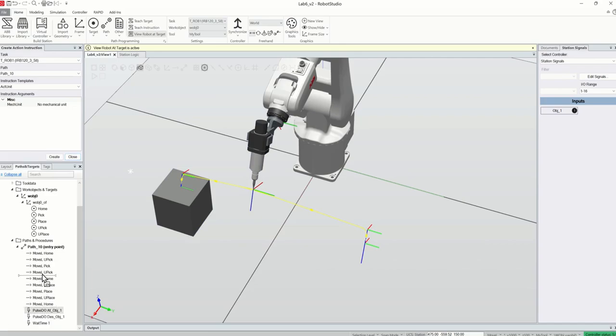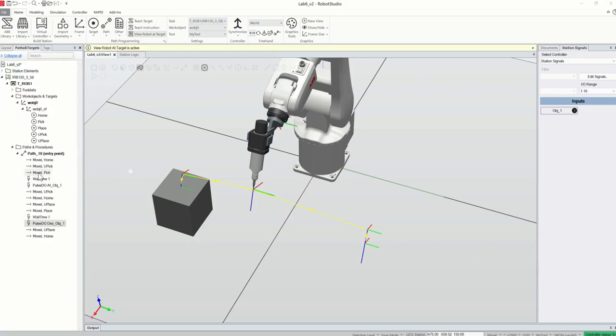So what I'm going to do is go to the pick position, then wait for 1 second, and then pick it. Likewise, I can do Control C, Control V. I don't need to go back to that instruction again; I can just copy and paste here. And it looks like I would need to go here, meaning from the approach point I go to the place position. I'm waiting 1 second, and I'm asking my tool to release it. Once you are confident that your arrangement is right, you can synchronize again.